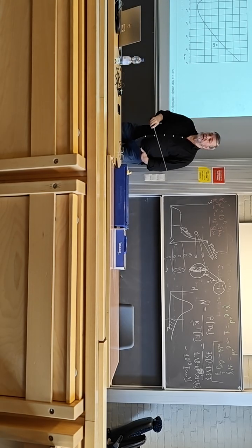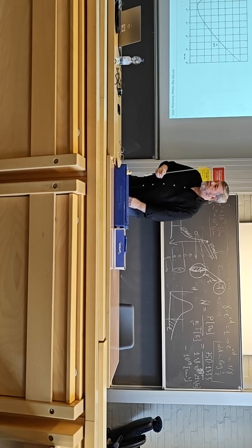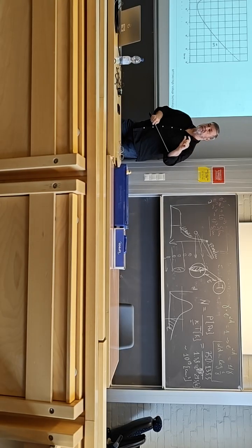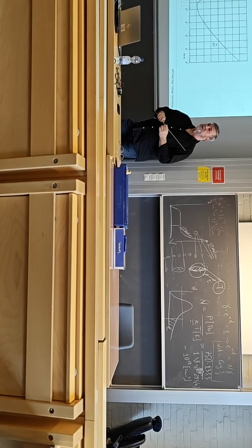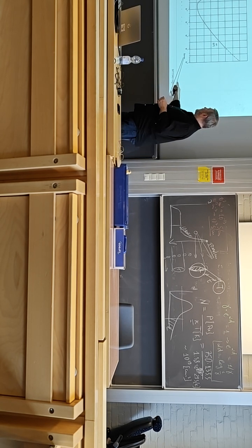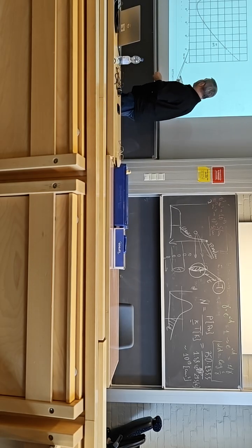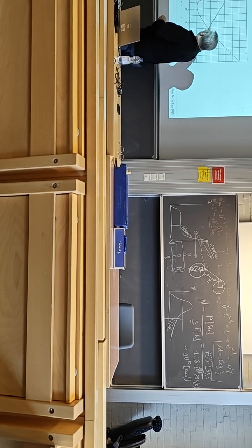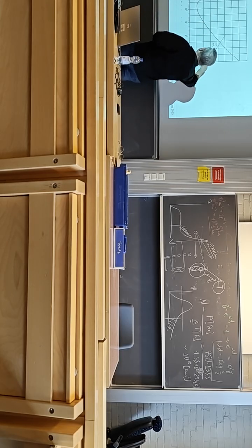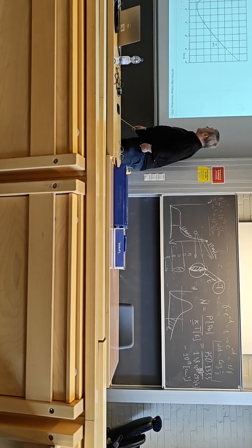And if you talk about normal conditions, we have pressure 1 bar, and let's take 1 centimeter, then we know that the breakdown voltage should be 30 kilovolt, right? So 1 bar multiplied with 10 millimeters, that will be 10. So we're here. So we could go here, and then we get, so 10, 20, 30, it's log scale. So 30 kilovolts, yeah, that's right.